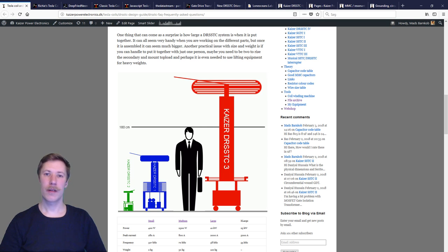But certainly do not buy any resonant capacitors that you cannot find a datasheet on, because if you do not know the numbers, then don't trust what is written on the eBay auction or so.